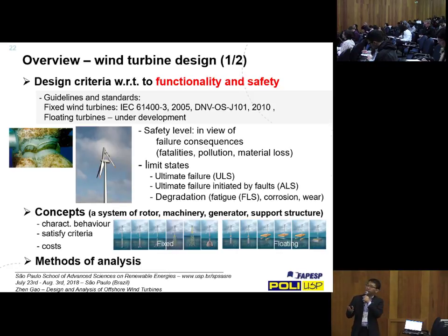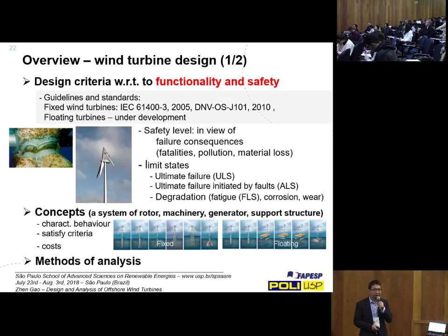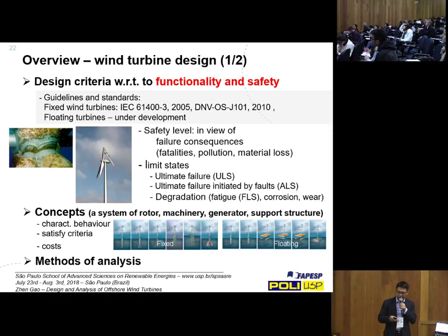And I want to point out one important issue, as compared to oil and gas platforms, and that is the consequence of failure. Usually wind turbines are unmanned structures, and when they fail, they do not really pollute. It's basically an economic loss when there's a failure in the system. And of course, you have many units in the farm, so if you have a global gross error in the design, then it will affect all of the turbines. That needs to be considered.